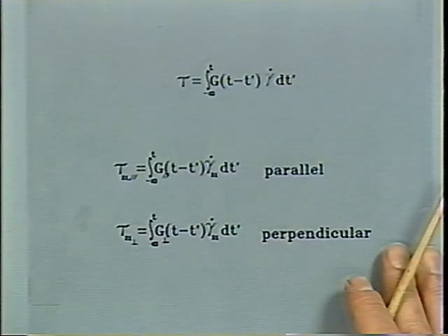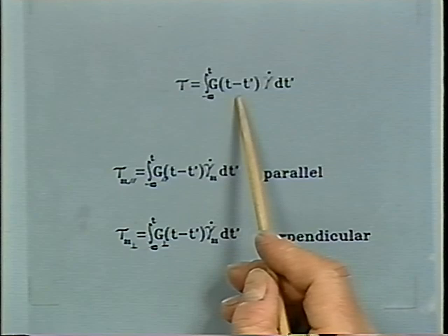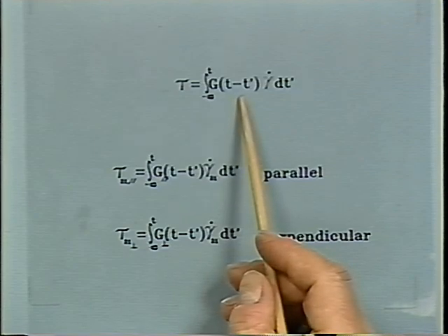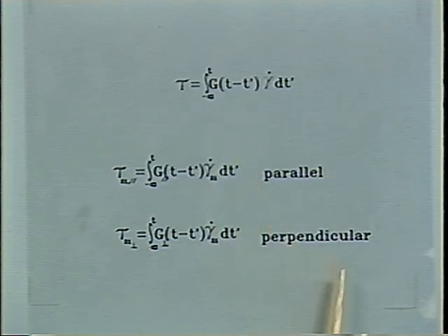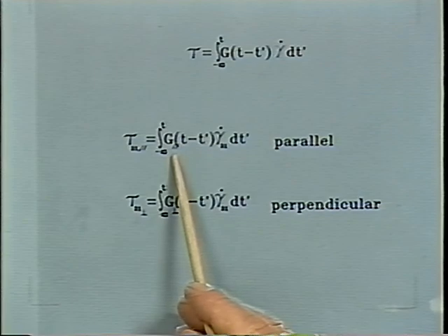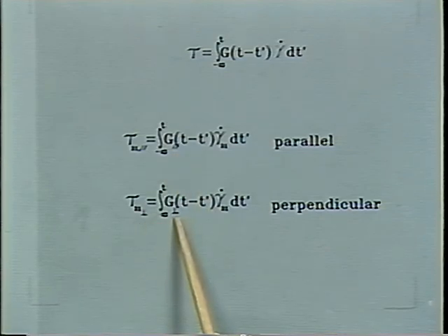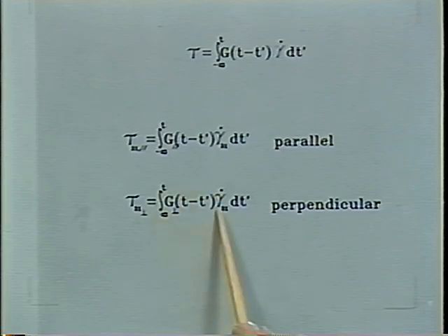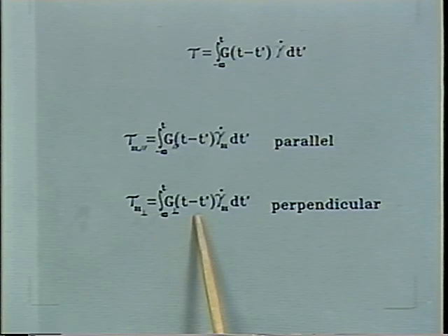See, we do a linear viscoelastic experiment, and in the isotropic case, it's enough to measure this modulus, and then you can predict flows of all kinds in all kinds of directions in the general case. But in our case, we measure this modulus when probing the sample parallel, and probably linear superposition holds when doing that, and when probing the sample normal to the cylinder orientation. And again, linear superposition might hold as long as we stay in this type of orientation.